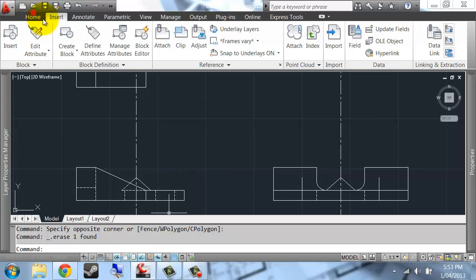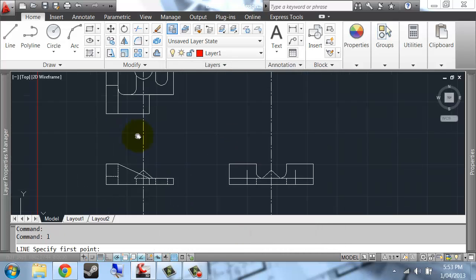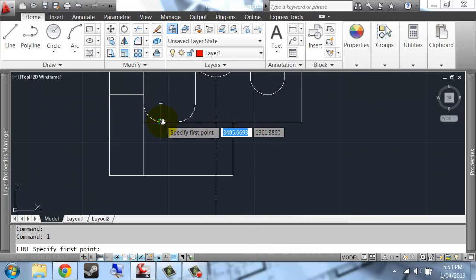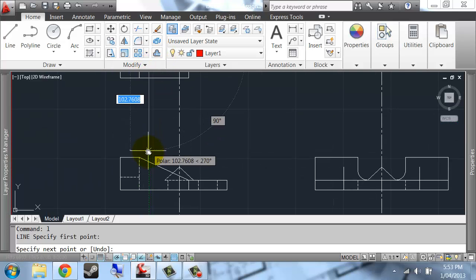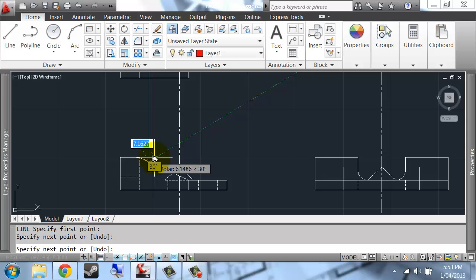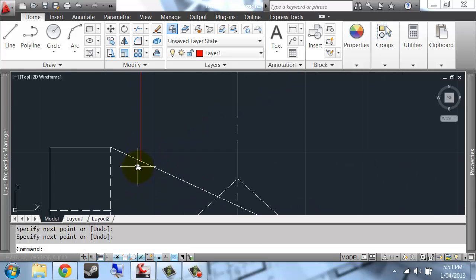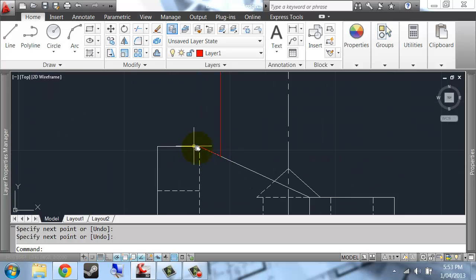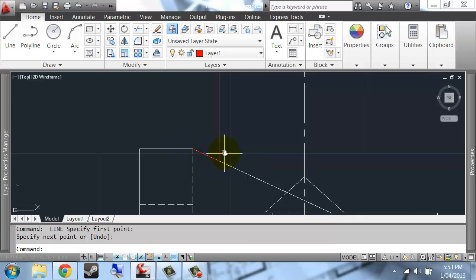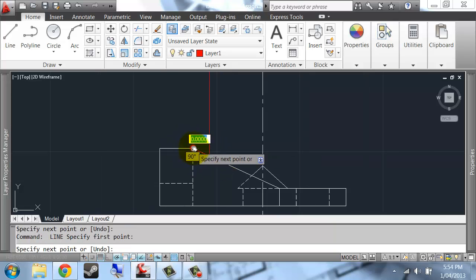Right, so the first thing to do is locate the edge of the circle in this view, the edge of this fillet we're talking about here, and run that down until it touches this part of the arc. So we now know that the circle we're interested in drawing in the view over on the right is roughly in this part of the elevation view.